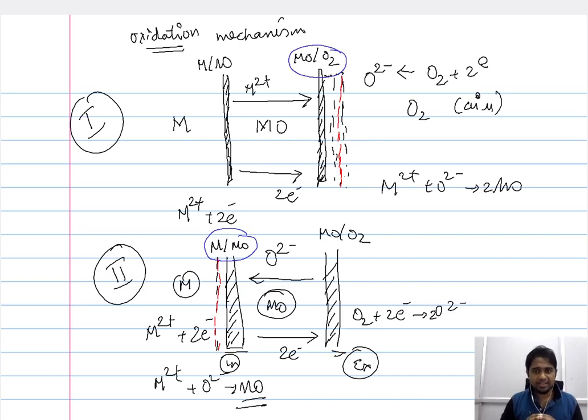So if we assume the formation of the extra layer of metal oxide at the external interface, the deterioration of it is nothing but the breakaway of this newly formed metal oxide. And when you have a breakaway, a migration that leads to the deterioration of the newly formed metal oxide, some sort of mobility or movement, it is influenced by the temperature. So in addition to influencing the kinetics of the oxidation by influencing the migration of the ions, the temperature also governs the oxidation mechanism through the stability of the newly formed oxides.